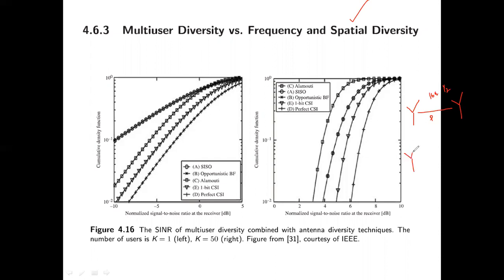Instead, say I go for one transmit antenna and two receive antennas. Suppose the first channel is bad, whereas my second channel may be good. Then I will skip the first channel from the first antenna, and use the channel where the situation is good, and I will use maybe 64 QAM and rate 3/4 punctured convolution code. So my throughput is very good. This is called spatial diversity.